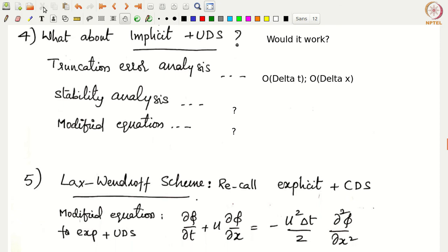They can be used for the solution, but the issue is that the upwind difference schemes are also diffusive, right? When we looked at the central difference schemes, they cannot be directly used either with explicit or implicit methods, but one property that the central difference schemes have is that they are dispersive in nature. However, they also have this artificial viscosity, the negative viscosity that is coming into play. However, they are not dissipative, so they preserve the amplitude, which is a good thing.